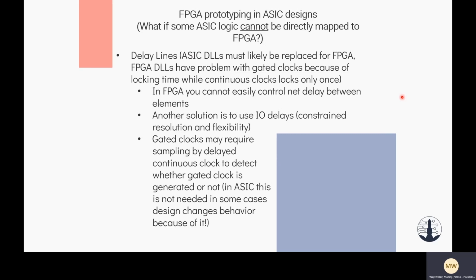Delay lines for ASIC can be implemented very flexibly, and can be hardened in fixed places on the chip. The length between all delay elements in lines can be very similar to each other. The routing between each element can be very similar, but for long lines it is literally not possible for FPGAs to be composed of so many delay elements with regular routing between them.